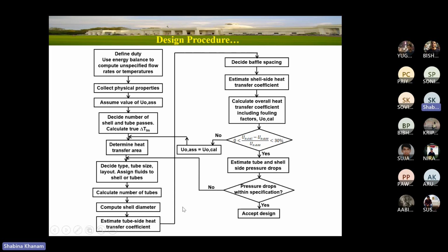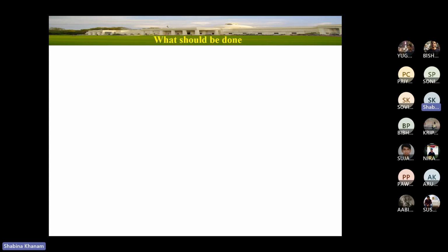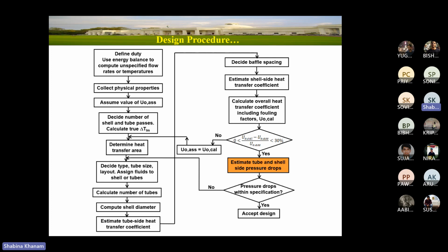However, if the tube side pressure drop is more, then instead of triangular pitch you can proceed with square pitch, and from here all the calculations will change, so you need to keep that in mind. Just try to bring the values within the permissible limit with the least variation. You need to be intuitive while designing. So that is about the design procedure.